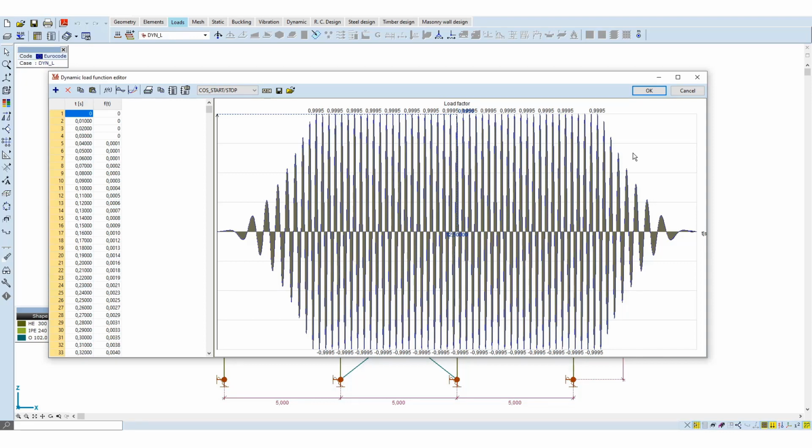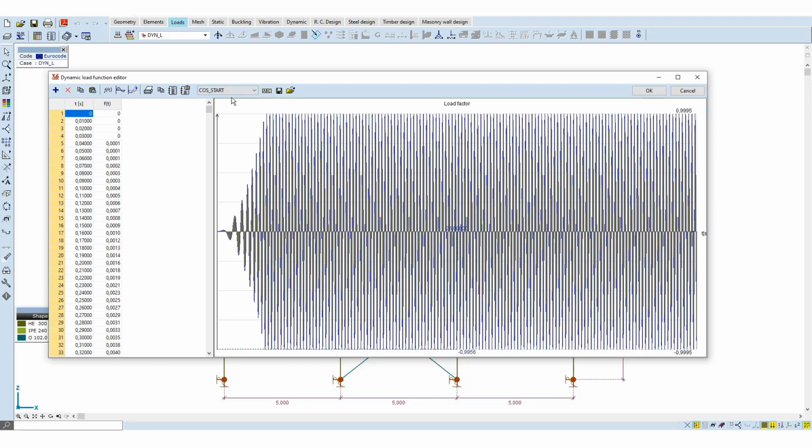After some time, the vibration is stabilized and we get the pure steady-state vibration of the system controlled by the external excitation. The start and stop phase can be defined only with integration, so it is calculated externally and imported in a tabulated form. Since the stop phase has a similar effect as the start phase, the latter is not modeled, to get a long period of stable, steady-state excitation and solution.